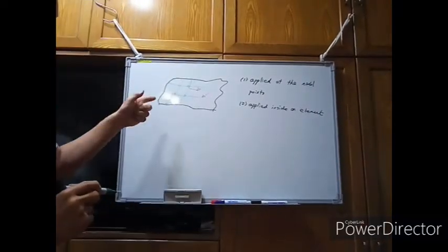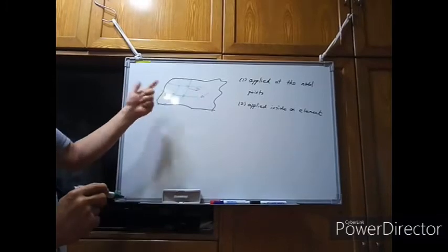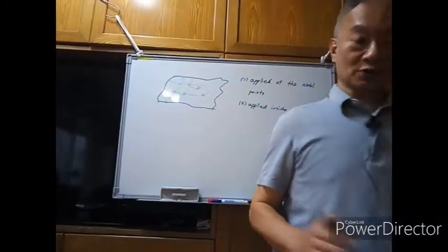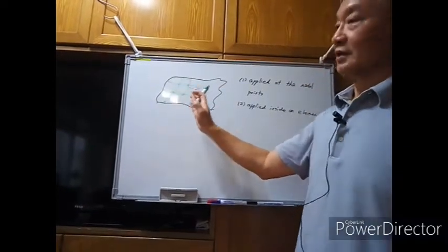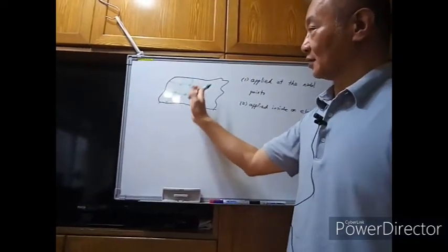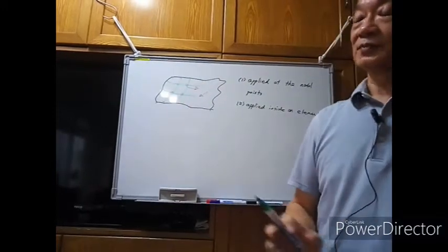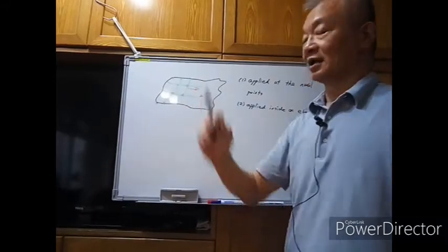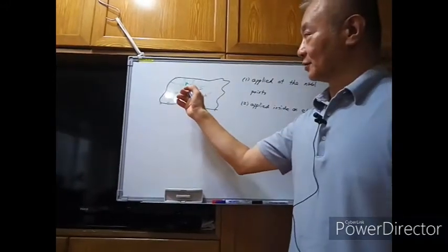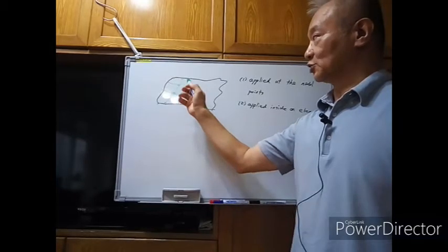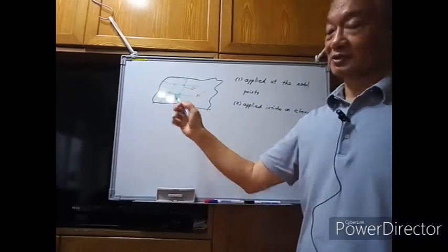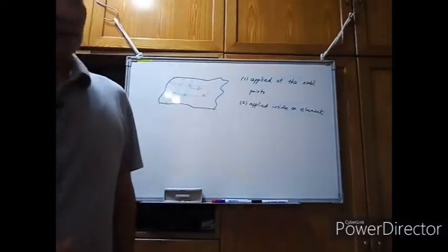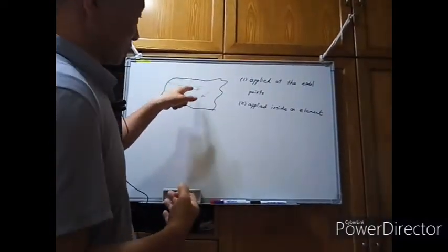So the program user has the right to determine where to cut the elements, and after you draw the boundary lines of the elements, also the intersections of the boundary lines are the locations for the nodal points.